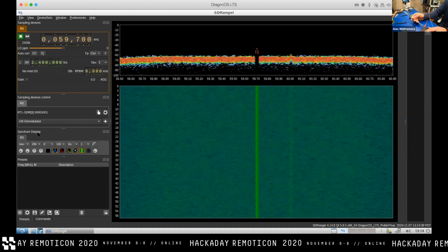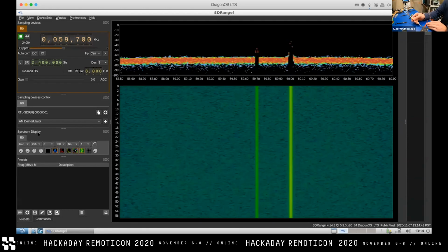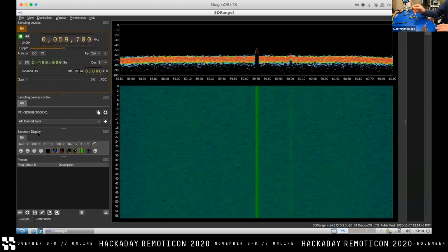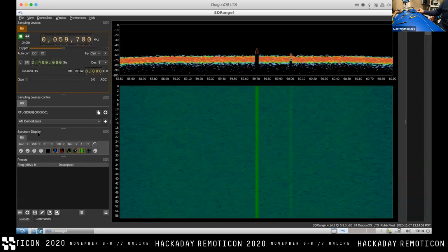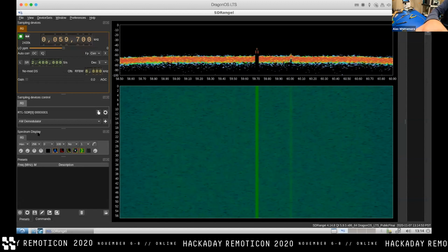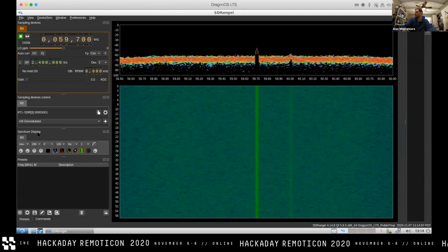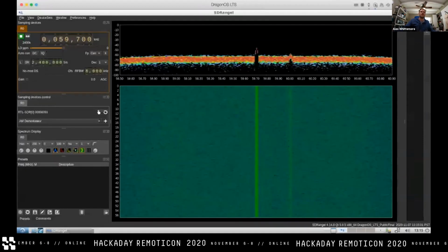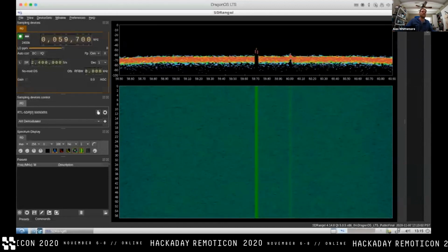So we've basically now built a tiny spatial resolution probe that can show us exactly which pin on the IC is radiating the noise in question. So let's go over and actually do this on the tiny FPGA side. My apologies that my tiny FPGA toolchain is on my actual Mac, so this might get a little bit ridiculous.